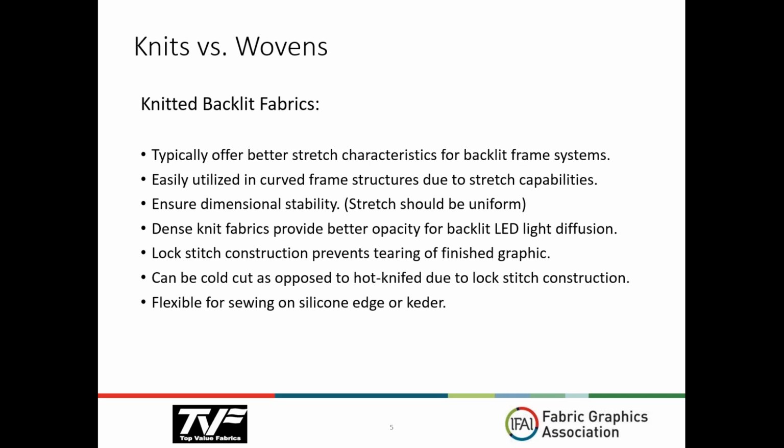One of the nice advantages about knit fabrics is that they can be cold cut as opposed to being hot knifed due to the lock stitch construction. And they're very flexible for sewing on silicone edge or teeter. And you'll hear that word teeter. It's commonly used, but basically it's the same thing as the silicone edge itself.